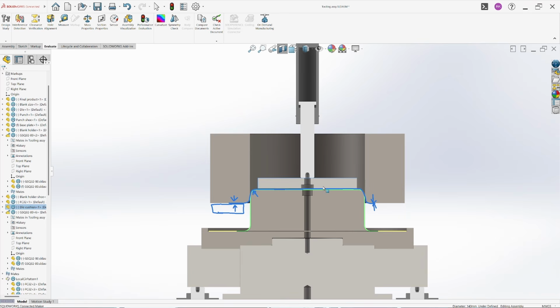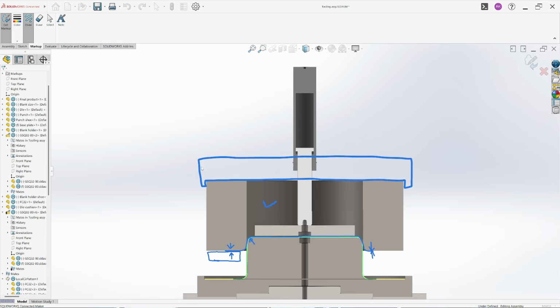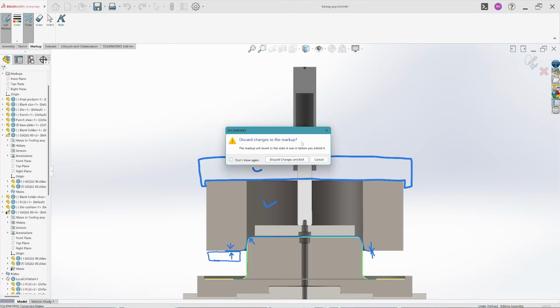Now what we can do is mount our gas spring. We can also use a die shoe, something like this, where we can mount our gas spring and this die too, right? And we will mount our die shoe to our pressing plate with the hydraulic cylinder, right? So first, let's quickly design this die shoe.